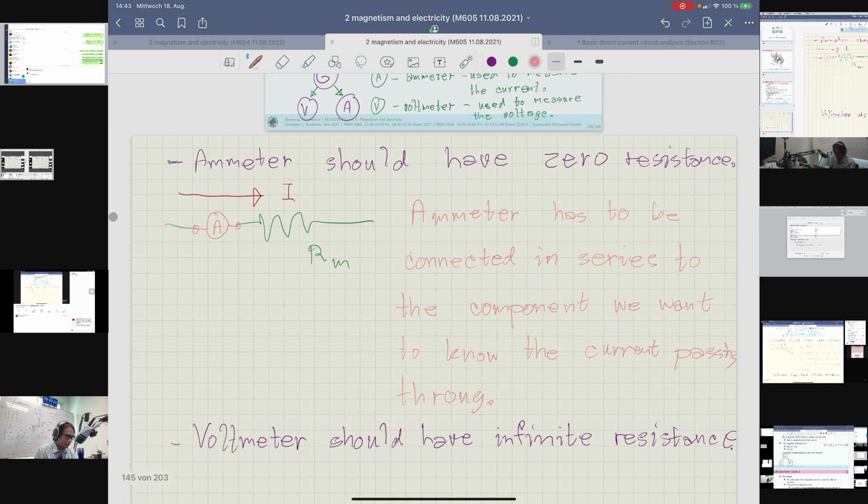Before that, there is only a single resistor Rm like this. In the second case, you have an additional resistor, which is a small value, so you have two resistors right now, and with the series connection of two resistors, it's going to be the summation of those two values, right? And if your ammeter has an internal resistor, it's going to obstruct the current flowing through this branch.